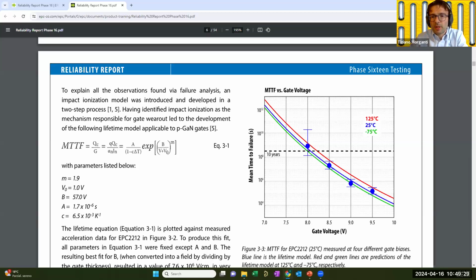And compared to Cascode, the structure is monolithic, is simpler, so is lower production cost, and it's also performing better. You cannot think about a cascode structure because of the parasitics of the structure itself with the speed of our GaNs. So the Schottky gate technology is what we are working on since several years, and I believe this is the best option.